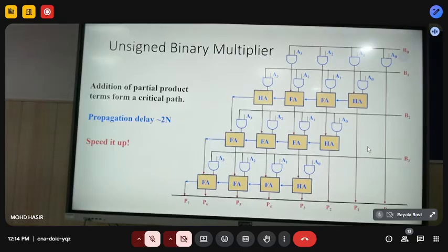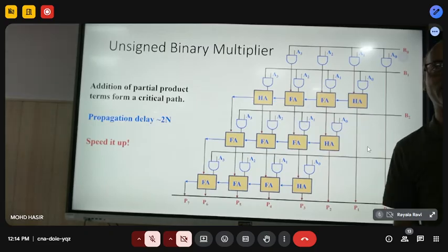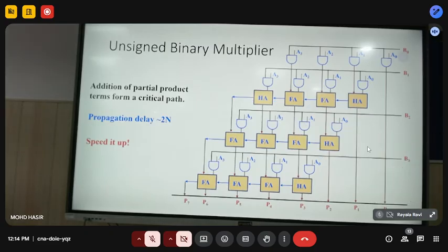So from a fabrication point of view, what should we do? We should look for all the half adders translated into full adders. Okay. Maybe some resources will remain idle. But then what is the advantage? You can use them as a fail-safe operation, right? So if some of the half adders on the chip are not working, probably you can multiplex and pass the input and get the work done instead of discarding the IC.